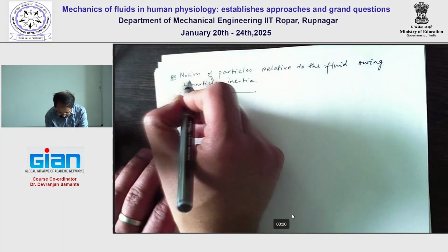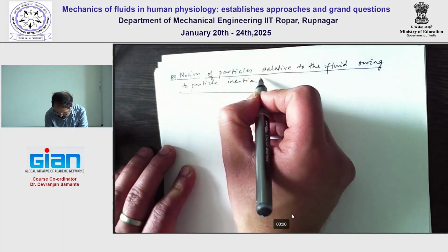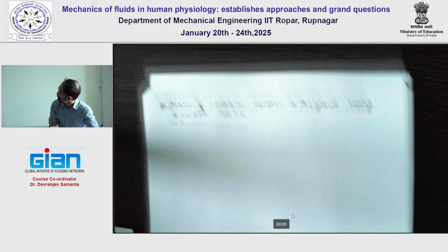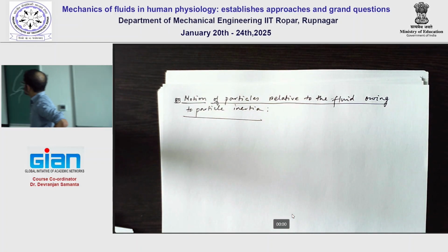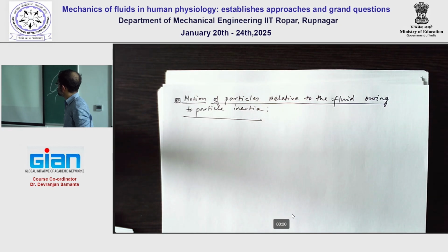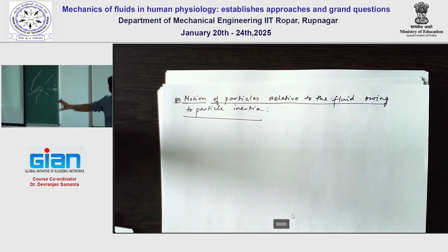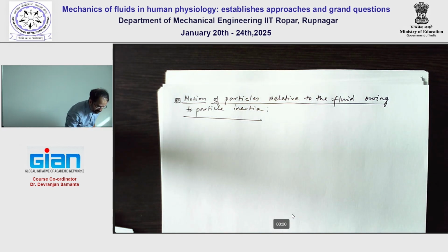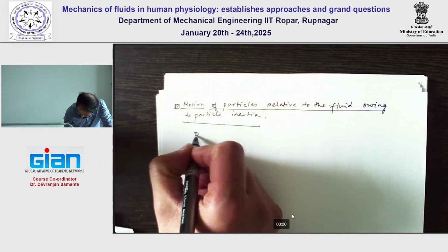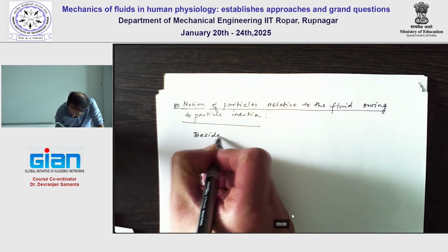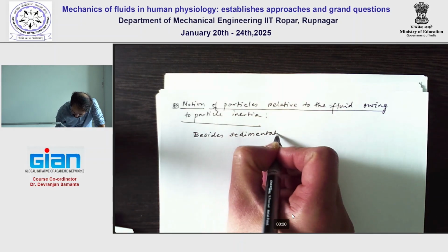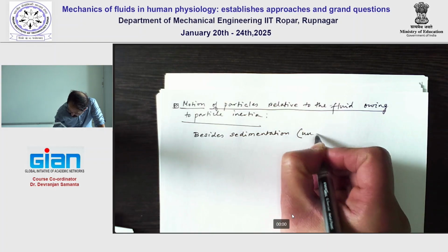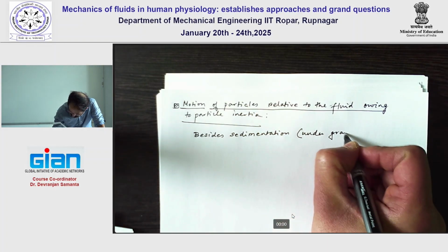So as I think I already mentioned, sedimentation is an important mechanism for regional deposition. The inertial impaction has to be studied as well based on certain parameters. So let me write down some comments before I try to develop the mathematics here. So besides sedimentation, which in our application would be always under gravity,